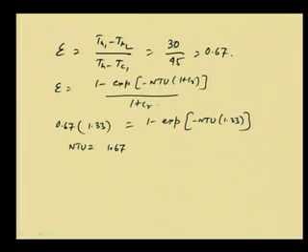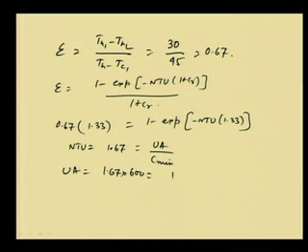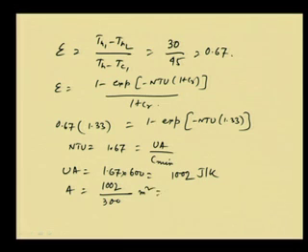So, this is the number of transfer units, and we know that it is equal to UA by C min. Then UA is equal to 1.67 into C min, which is the hot fluid case, into 600. So, this is becoming 1002 joule per Kelvin, and the area of heat exchange is equal to 1002 divided by the overall heat transfer coefficient, given as 300. So, this is becoming 3.34 meter square. So, this is the area of the heat exchanger.